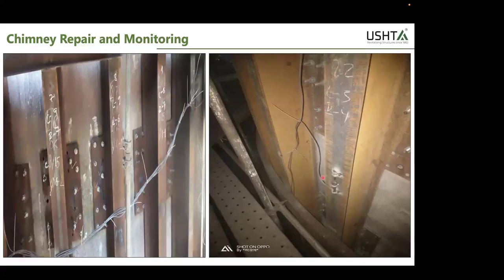We'll do a lining which can take temperature up to 1000 degrees, and that's how we can reuse this structure without even increasing any kind of dead load, because the present lining is about 500 mm. So we'll reduce it to 400 mm, which can take 1000 degrees, and in 100 mm we'll do jacketing. So that would probably be say 80 to 90 days project for us.